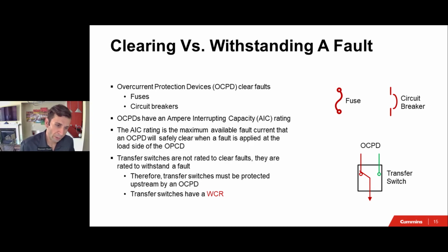So transfer switches, since they are not designed to break the circuit, must be protected on the line side, upstream of the transfer switch, by an overcurrent protection device. Transfer switches have what's called the WCR, withstand and closing rating. Let's derive that WCR.